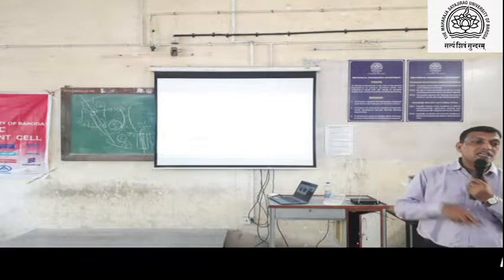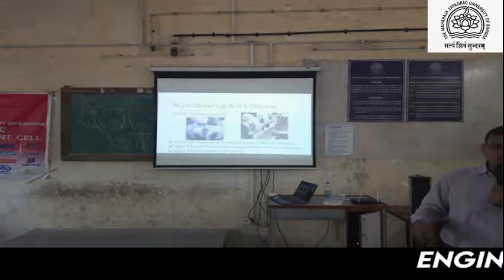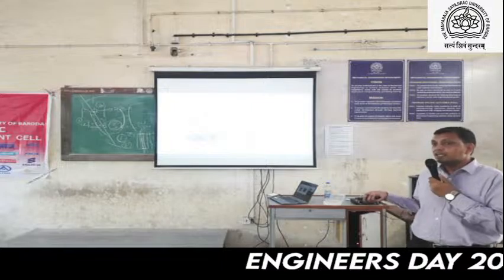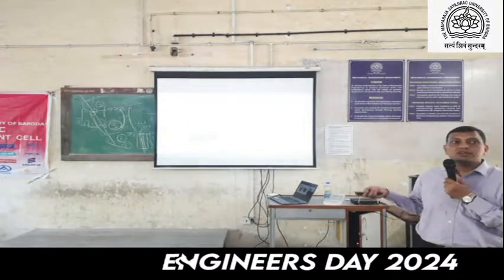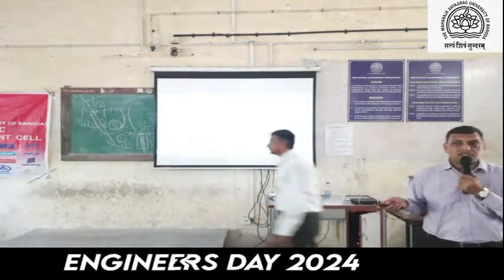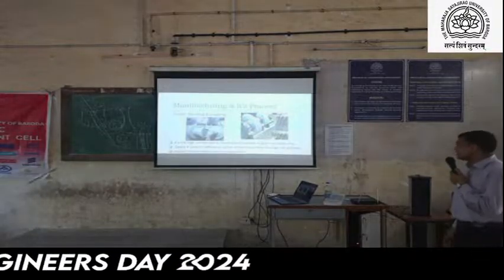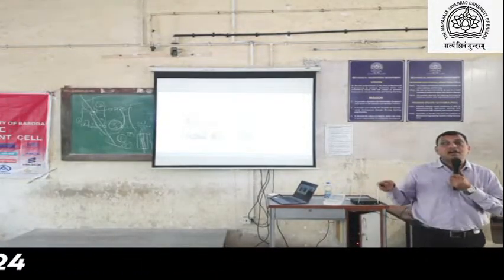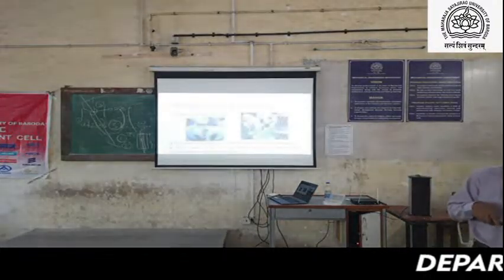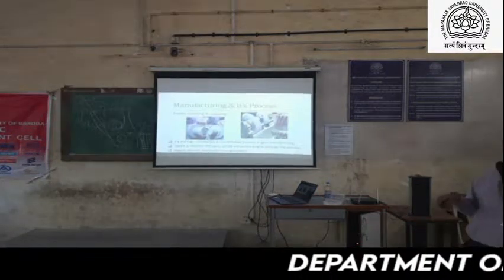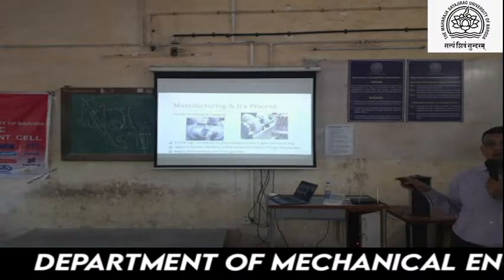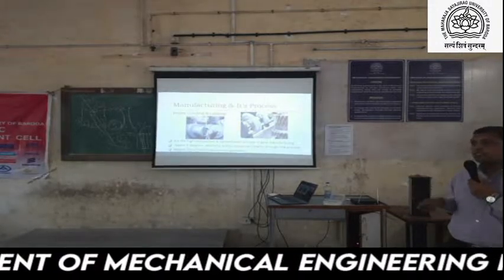Whenever we go for high speed applications, like turbine gearboxes and gears, we require a higher accuracy class, so we have to go for class 4. Based on the accuracy classes, we require a high efficiency machine. Not every industry can manufacture class 2 or class 4 accuracy gearboxes.